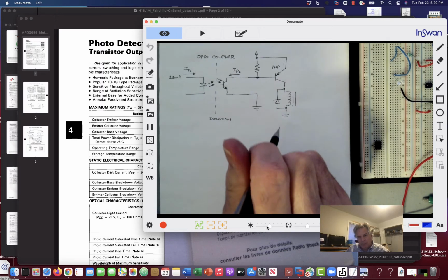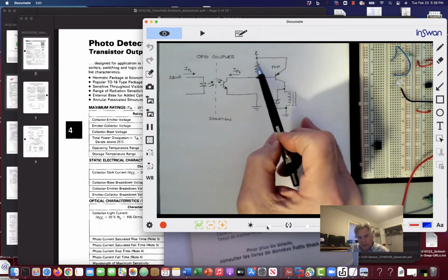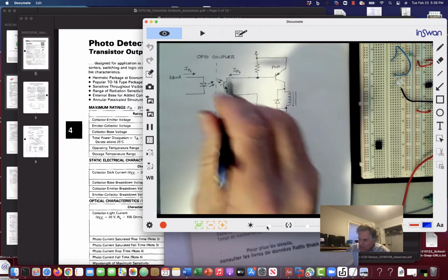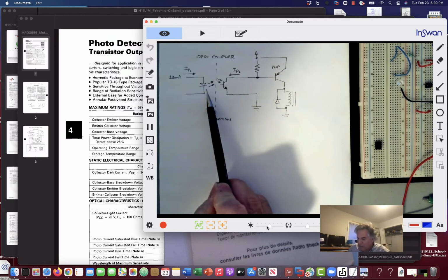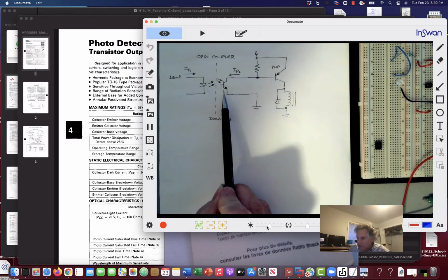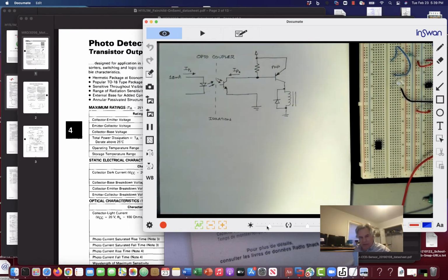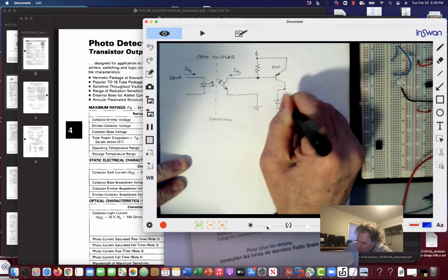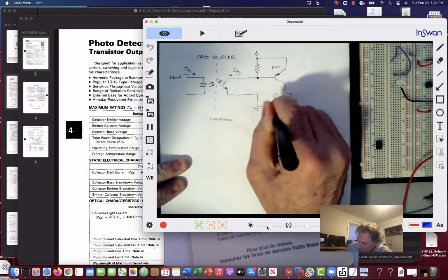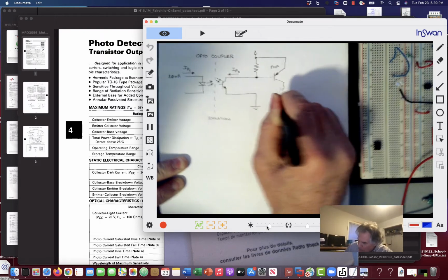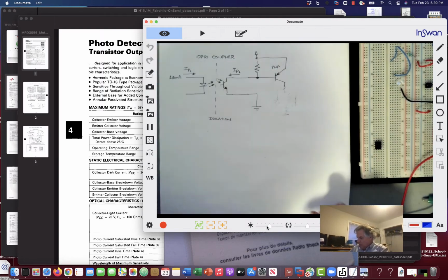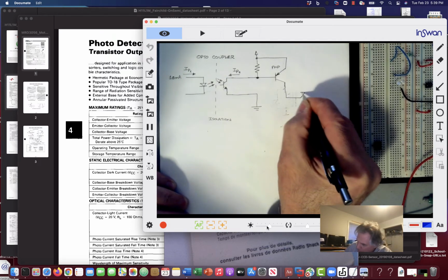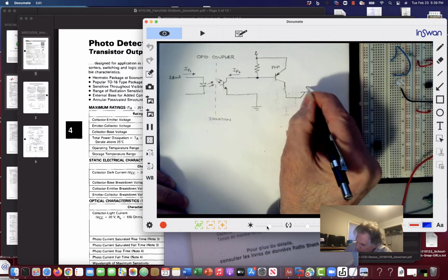This relay might operate off a supply, maybe 40 volts over here or something. This relay achieves a similar thing to what the opto-isolator does. It has isolation between the input and output. So we might not even want to use a relay. We might use something like an SCR, where maybe we'll inject current into an SCR.